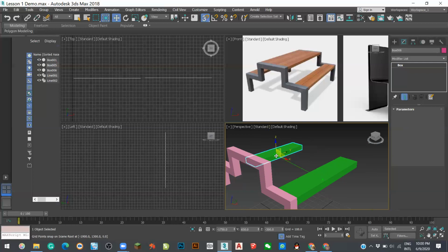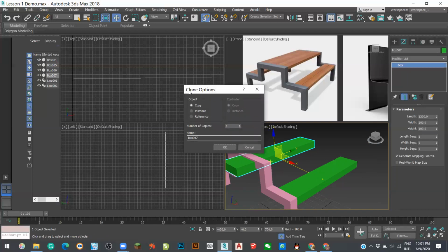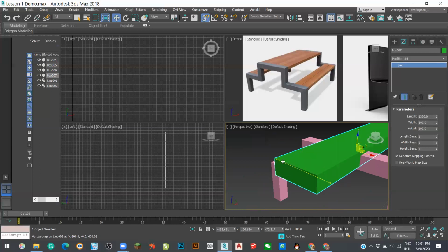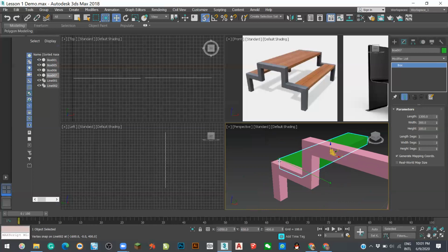Okay, you will see the yellow color, which means it's not correct. Okay. Never mind. I just click and release all. It will ask you to clone option, either copy, instance, reference. Okay, I select copy and click OK. Later I will tell you what is the difference. Okay, same. My mouse shift to here will turn to the yellow cross and click. I click and hold and move to here will turn to green. I mean it snaps to this corner, so release. Okay.